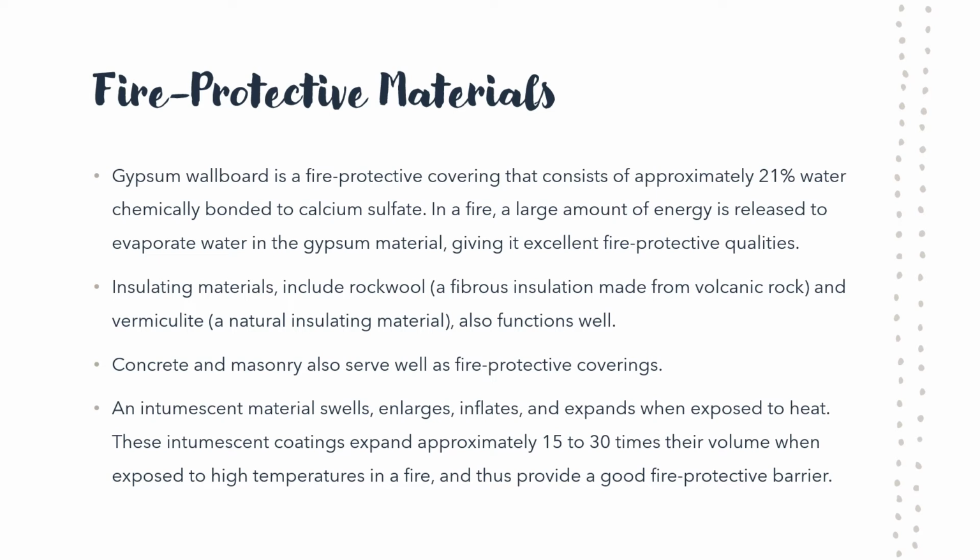An intumescent material enlarges, inflates, and expands when exposed to heat. These intumescent coatings expand approximately 15 to 30 times their volume when exposed to high temperatures in a fire, and thus provide a good fire protective barrier.